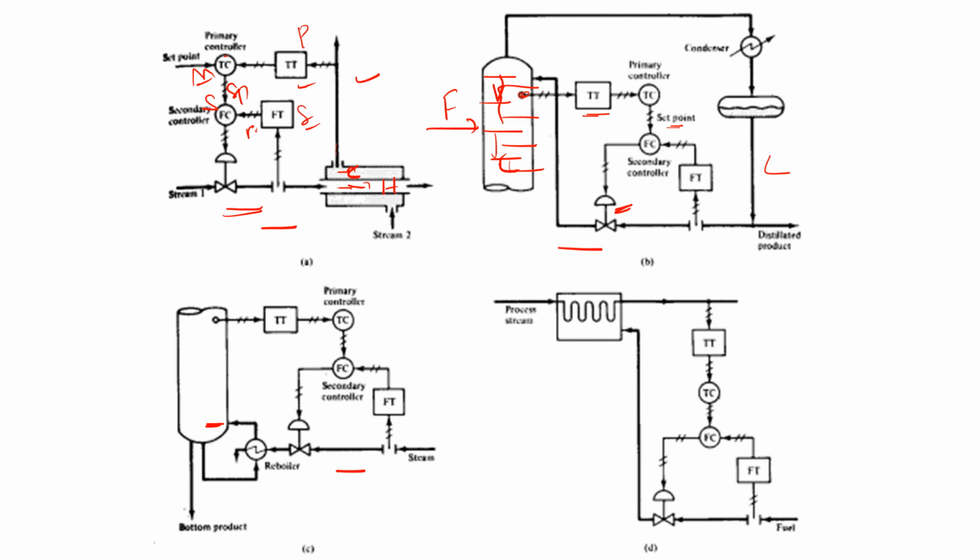Similarly here, the bottom product. So here we have vapor, here you have liquid. So once again, boil the liquid, it is converted into steam. So that's why we have a reboiler. So here this is liquid and it's also liquid. After reboil it becomes vapor. Then once again you feed it. So likewise this process continues.